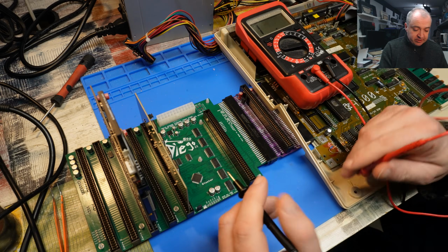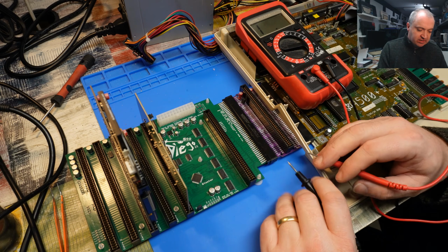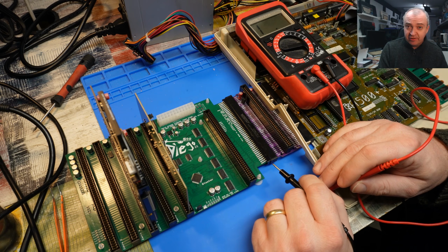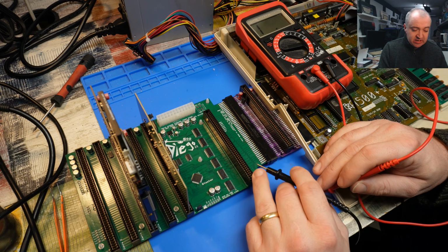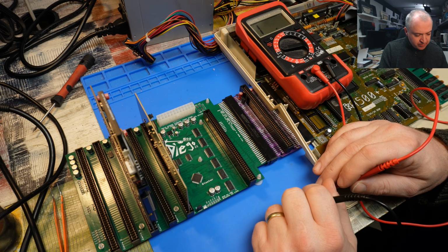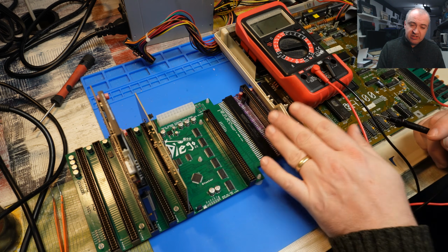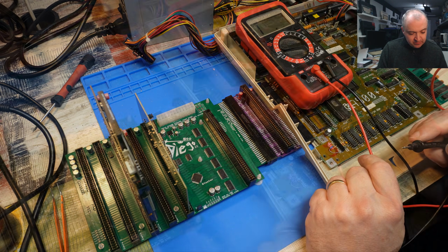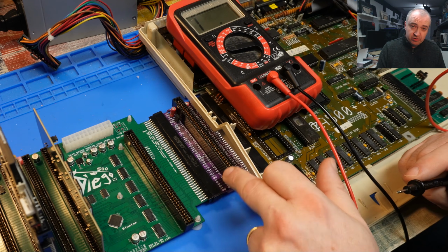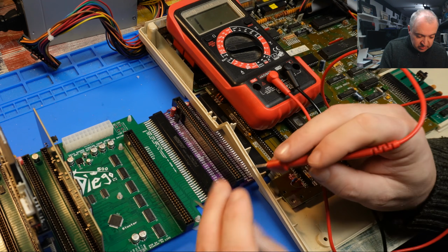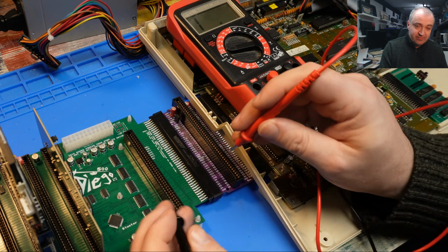All right, I think I figured it out. Doing a bit of testing here, and don't ask me how, but it seems I've got two of the pins reversed: address lines A21 and A22. I plugged in this CPU breakout board. Remember I showed you this in the intro to the video. That is essentially another one of those, but it is just straight through all that. So everything should more or less line up.